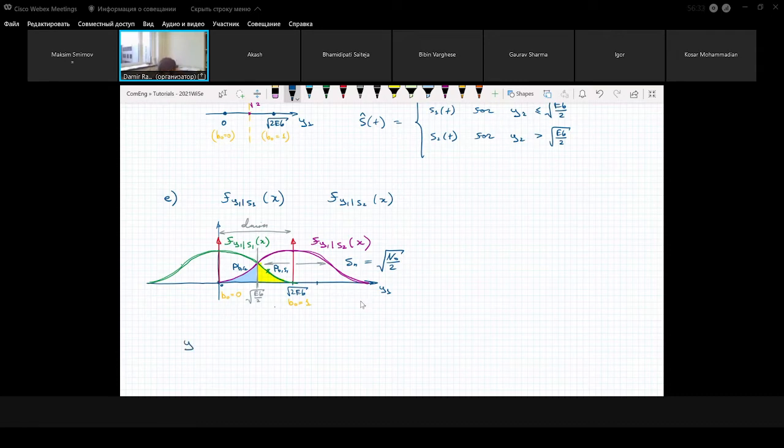So we have y1 equals the integral from 0 to TB of my signal, square root of 2EB times Bn times psi 1 of t, plus the noise n(t) times psi 1 of t. So this is the transmission of the signal, and also we have noise. And then we calculate the correlation with the reference signal.